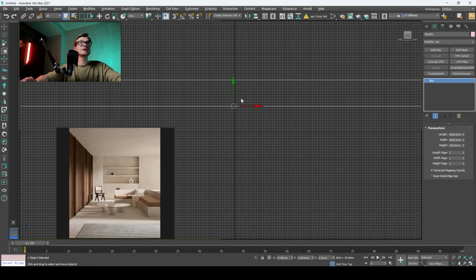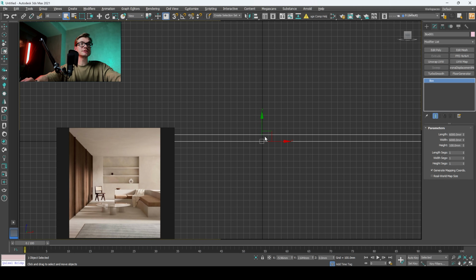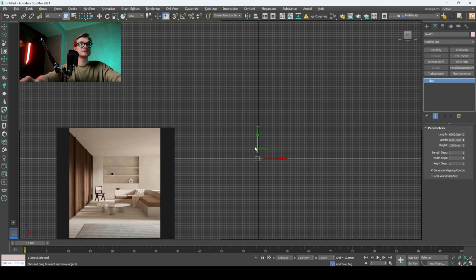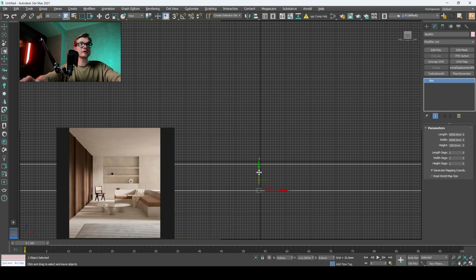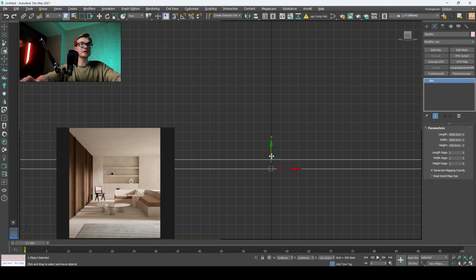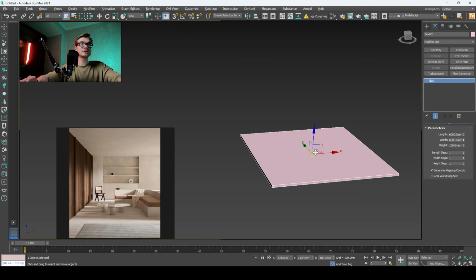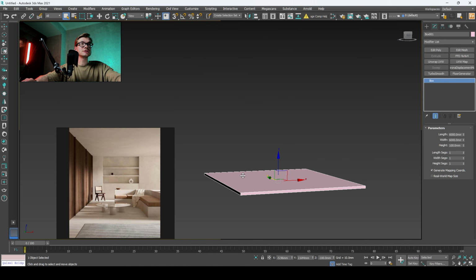Let's take a look at where it is placed on the frame. I would like to make our floor start at the 0 level that goes right here, and I can do that by indicating -100 on the z-axis. Great, now we can move to creating the walls that are placed right here.